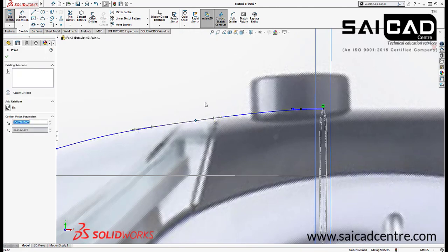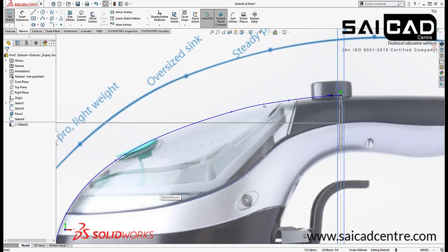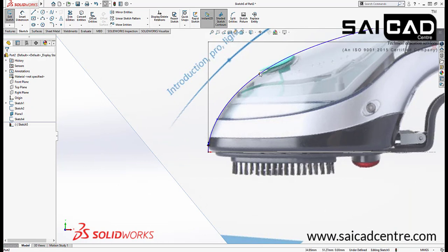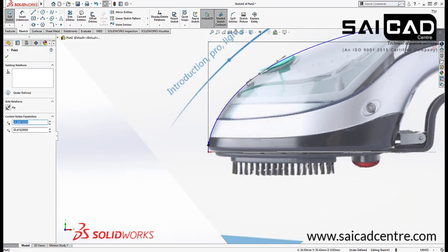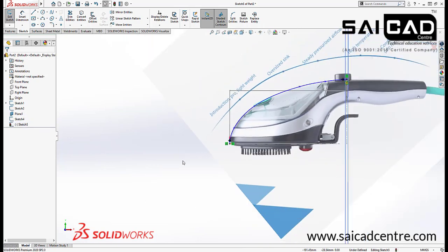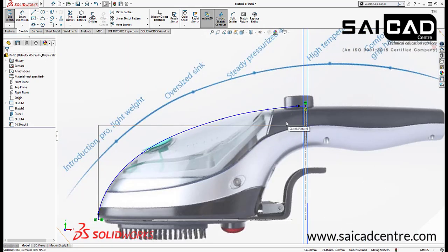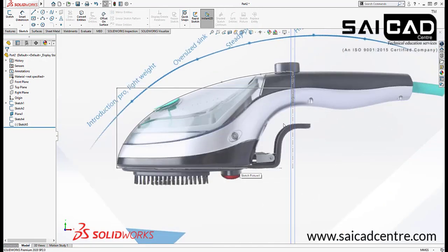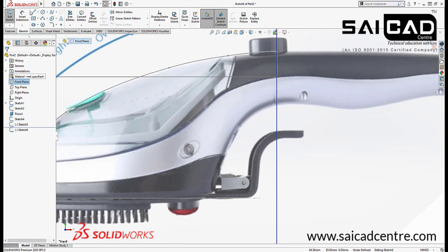You can just manipulate it a little bit so that the curve remains smooth like that. You can control the vertex directly from here, but I just don't want to do that, so that our shape remains similar. So for this spline, don't make it fully defined. If you can, you can do that, but I like it to be like that. Just exit out, and for the bottom shape I'm just going to use another spline in a similar fashion like that, and going to use again.